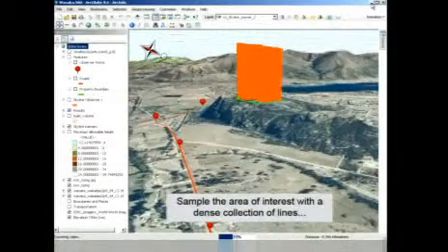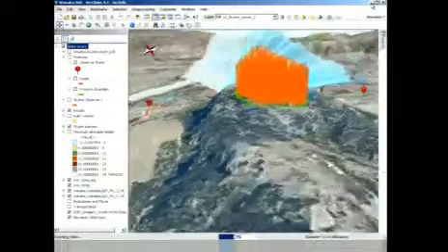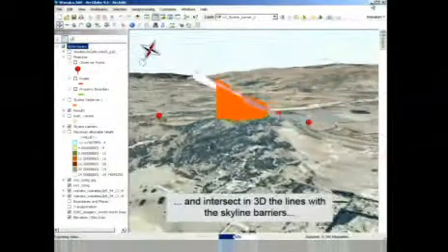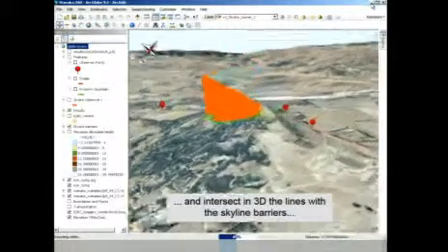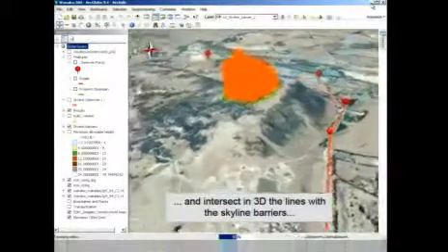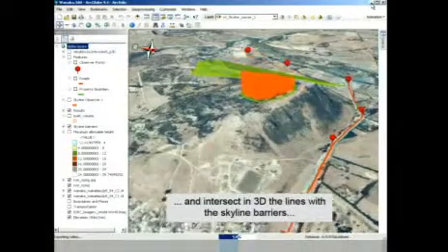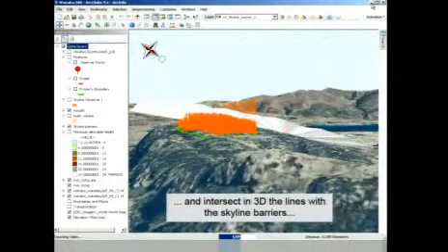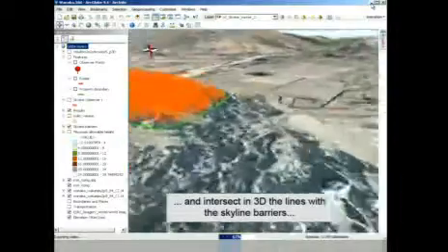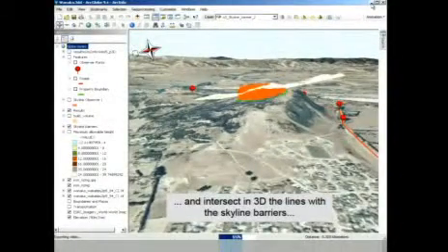so-called vertical lines, which are sticks. The reason I'm using these vertical lines is that in New Zealand, they go out and place wooden sticks on the property, and then you have to drive around and see if you can see these sticks. So I thought I'd use sticks here as well. And I'm cutting these sticks with my visibility planes. And, of course, the more times you intersect, the more accurate your analysis becomes. But in the end, we're going to end up with a whole bunch of vertical sticks that can't be seen from my public road.